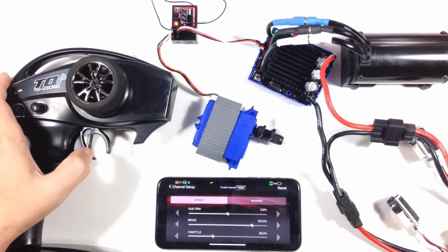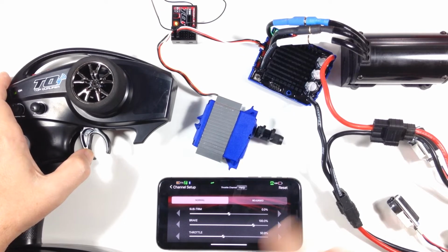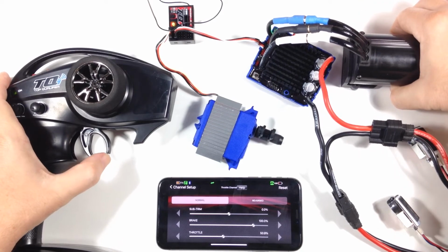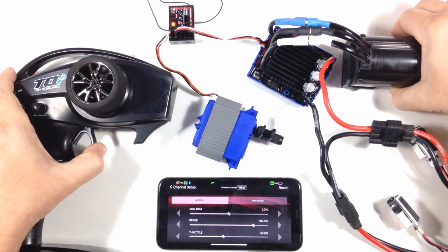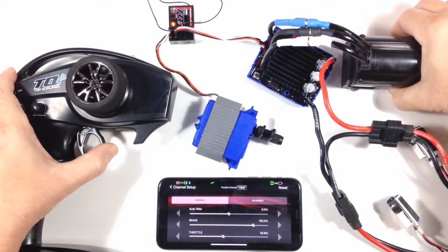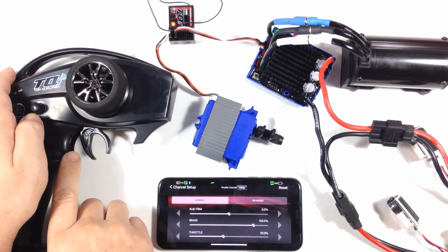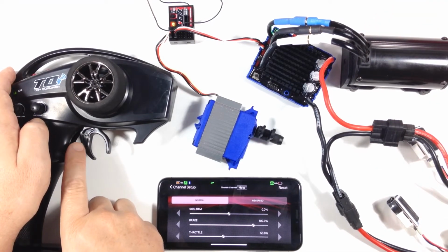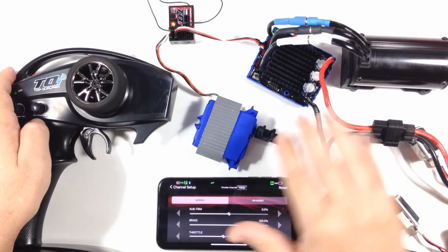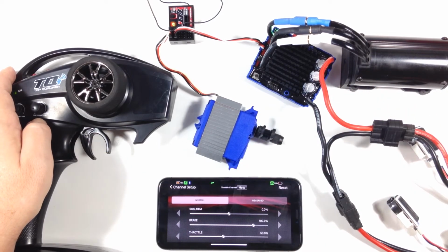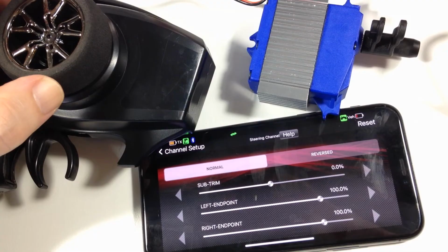And if we set, well, actually it goes weird if you set it too low for some reason. So now we got 50% throttle, but you can see it's only hitting that 50% at full trigger input. So it's remapped that reduced throttle travel to the full trigger input as normal.